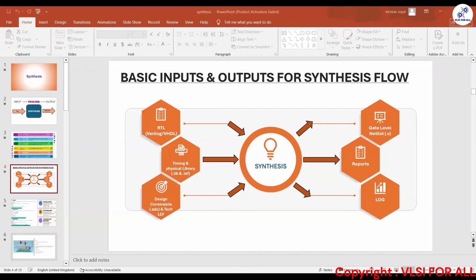They look at how your test coverage is, because it's not really possible to convert all the flops into scannable flops. There is a disadvantage: ahead of every flop you have this mux attached, so your area increases. So they have a percentage requirement that the majority of the flops will be converted, and the ones that are not of that much use, we'll keep as a normal flop.